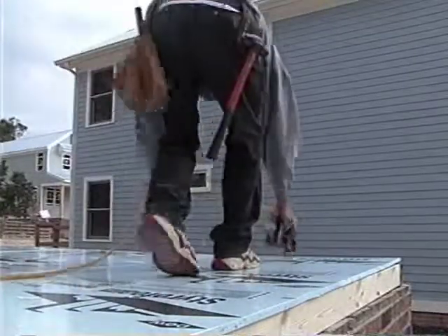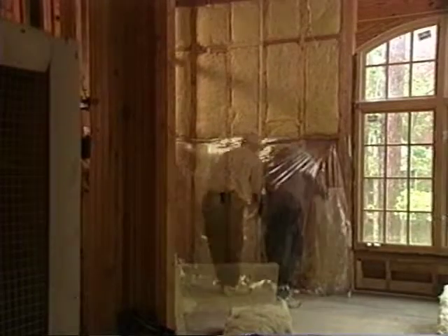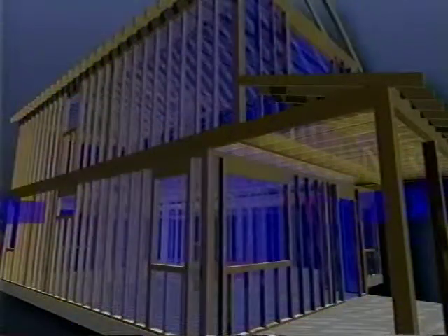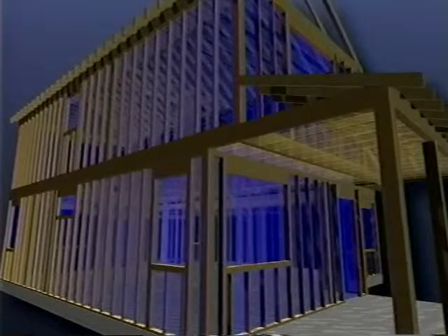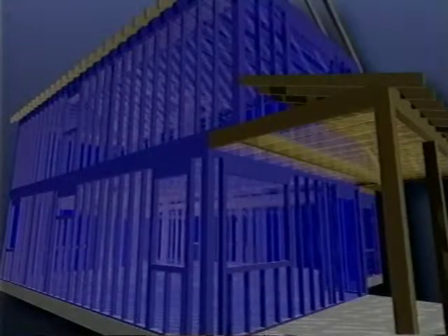We've talked about air barriers, which prevent air leaks in a house, and thermal barriers, which slow the flow of heat. Now a word about vapor barriers. Vapor barriers protect insulation and other materials by preventing unwanted moisture from seeping into a wall, ceiling, or floor assembly. Water vapor moves from warmer areas to colder areas, so where we put the vapor barrier depends on whether we do more heating or cooling of a house. If we do more heating, it goes on the inside of the insulation. If we do more cooling, it goes on the outside.